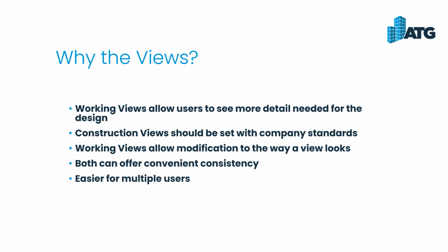The construction views should be set with company standards. How you typically show views on sheets should be standard, whether it be Revit or AutoCAD. You want those to look as similar as possible. So we go in and set up view templates so that we lock those construction views down.